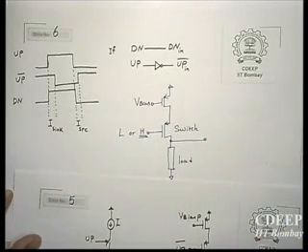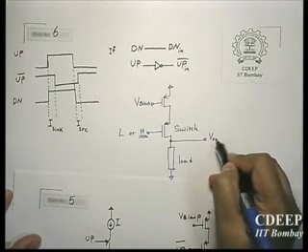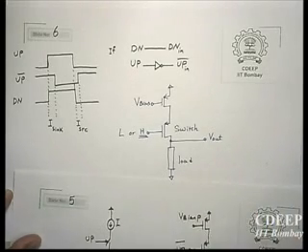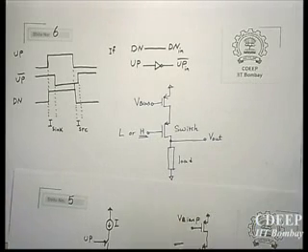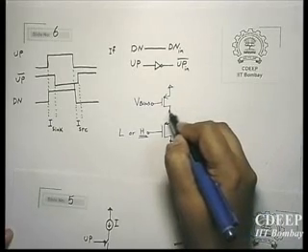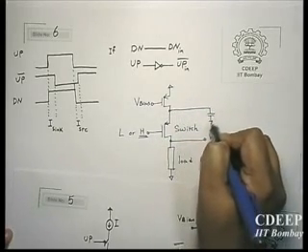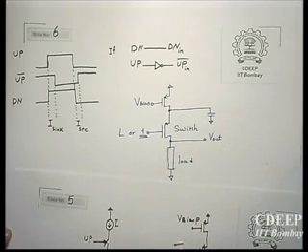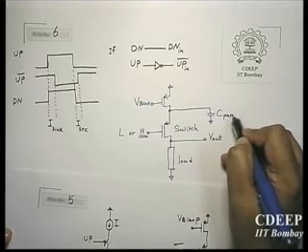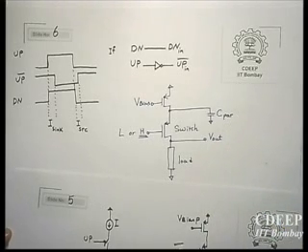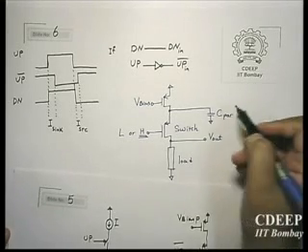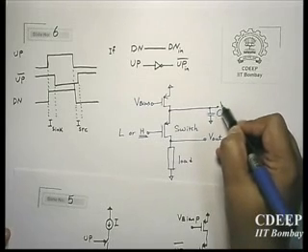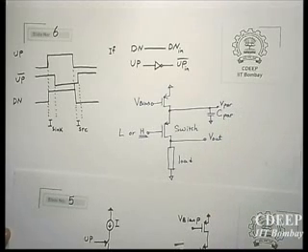So first of all, your output voltage is practically 0, of course. It depends on what kind of load you have. If it is a capacitor, it stays at some constant value. Anyway, it remains at a constant value. What will happen for this node? This is connected to a parasitic capacitor, so this is C parasitic. Therefore, the current source continues to charge that capacitor. So the current source continues to operate. As this capacitor gets charged, the voltage on the capacitor slowly will rise and will approach VDD.